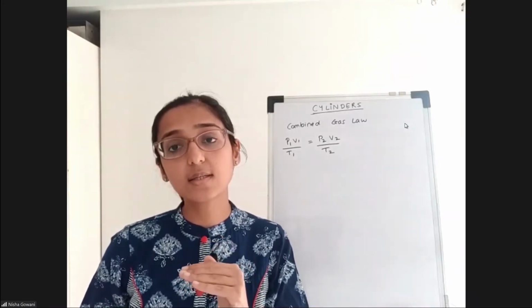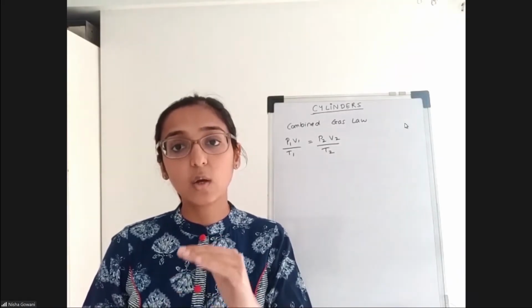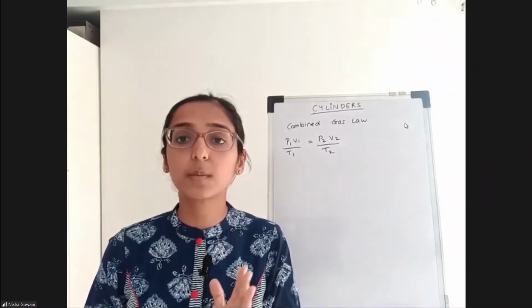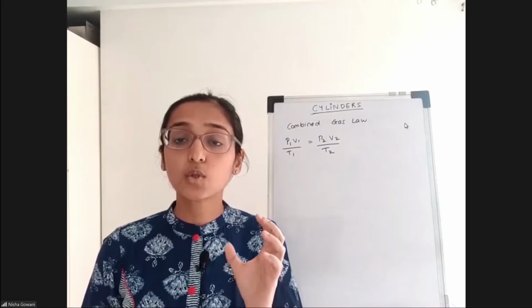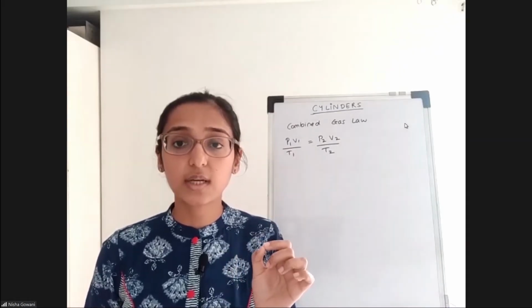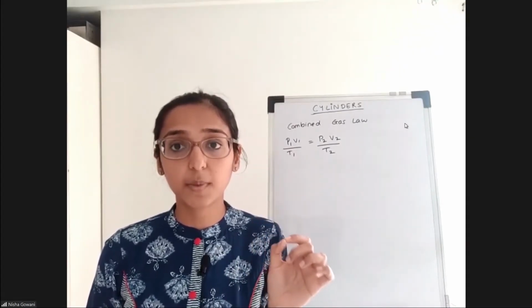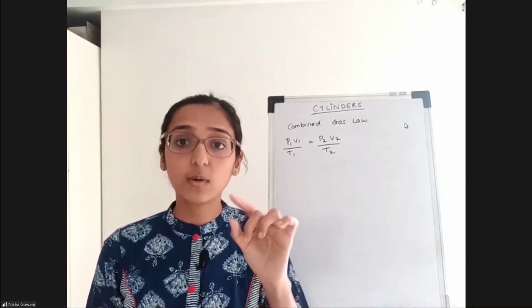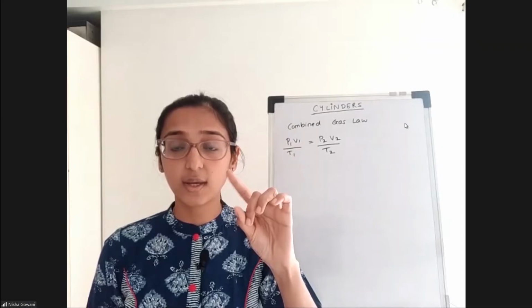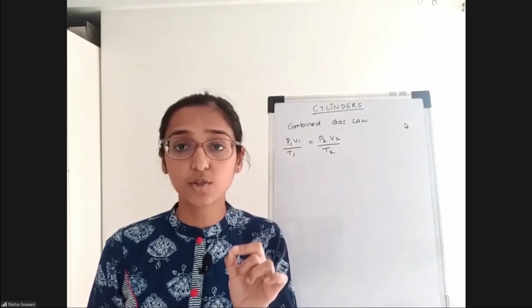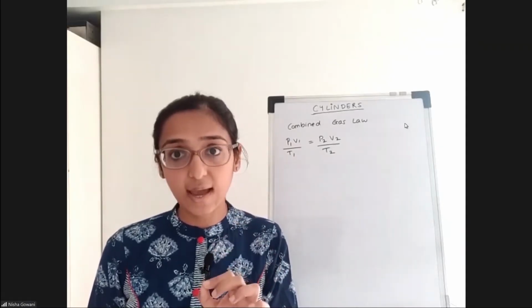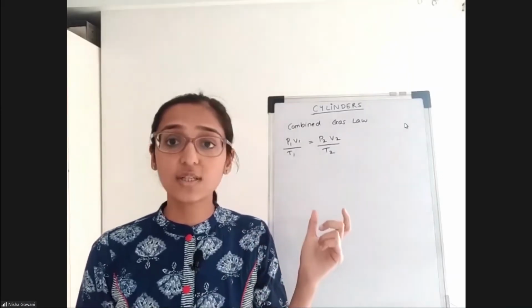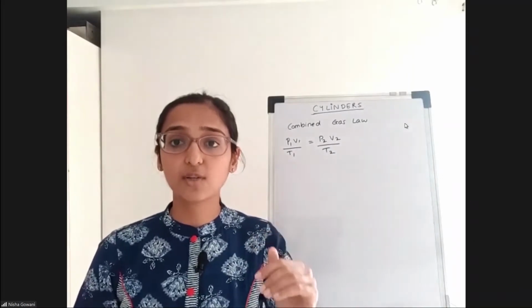So there is going to be some amount of nitrous oxide in the gaseous form within the cylinder, and the remainder is going to be in the liquid form. So what pressure will be read on the nitrous oxide cylinder? It will be the saturated vapor pressure. It will be the vapor pressure of the nitrous oxide that will be measured on the pressure gauge. It will not measure the actual pressure of the nitrous oxide gas. Whereas the oxygen cylinder has got only pressurized oxygen gas.